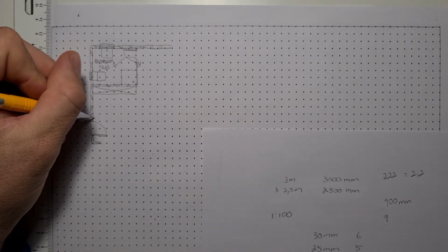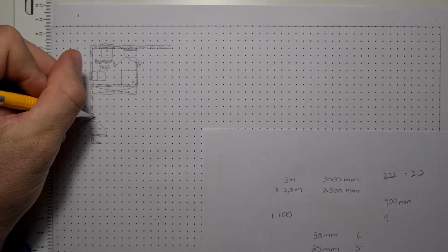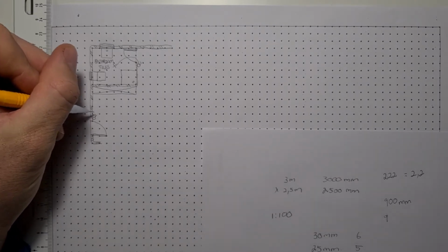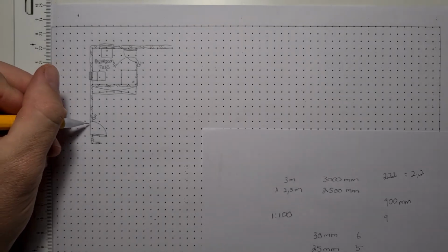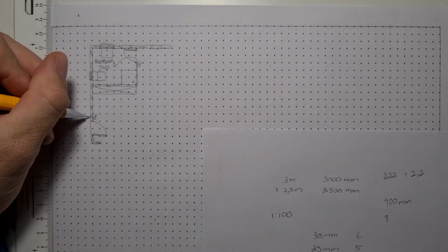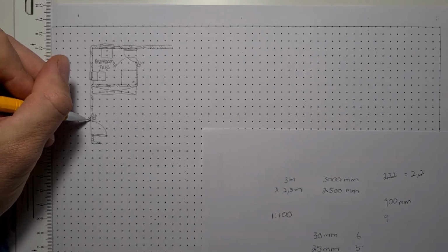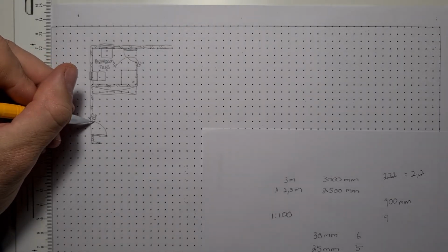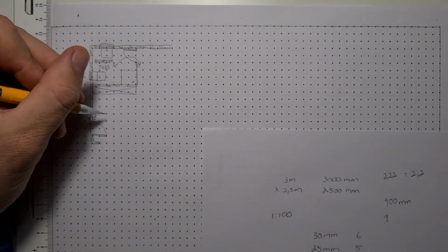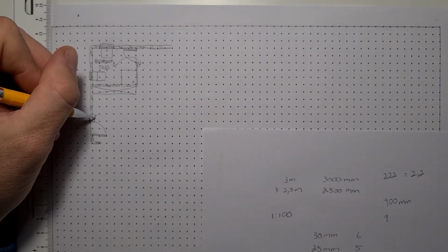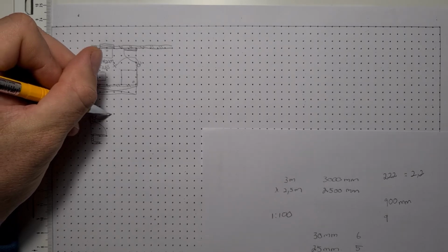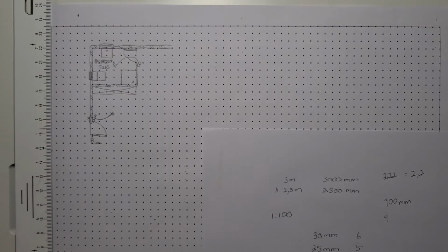For an external door, there should be a line over there. The light switch will be on the open inside of the door. I'm going to put in 2 switches over there. I want to put in an external wall mounted light over here, so I'm going to draw it in there. And I want to add another light over here to switch on this section. Right, so there's a few symbols used, and then obviously my labeling.